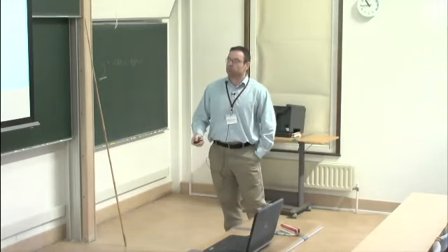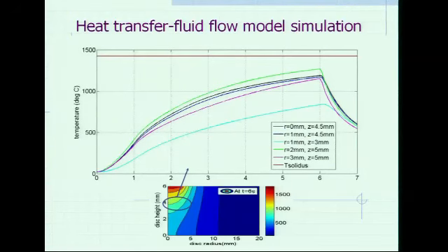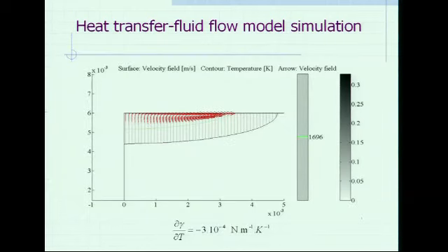Well, this is just to show you some measurement at different points of the geometry. So not in the whirlpool size, because I won't be able to do it later, just around, to show you the evolution of the temperature. And this one is the solidus temperature, when the solid is starting to melt. So here it is what we expected in this modeling.